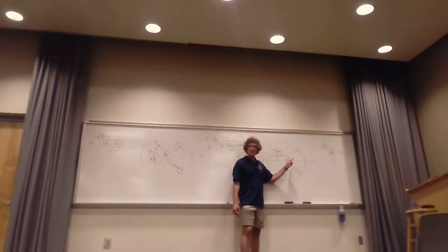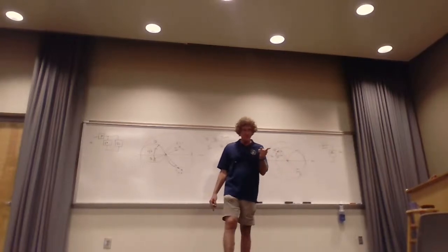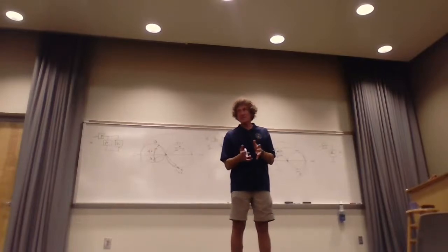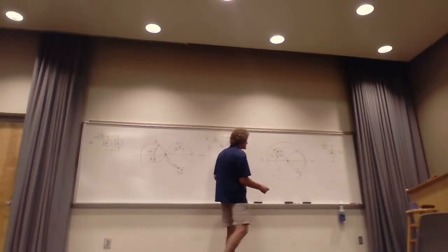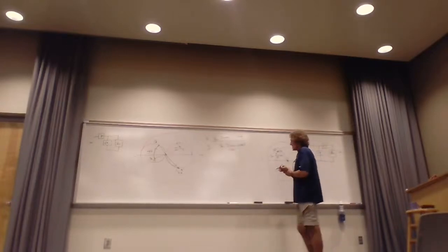Y'all follow me on that, class? Does anybody not follow me? Okay, remember that. Admittance, right? The inductance, if you add it, would be a minus j. The capacitance would be a plus j, because admittance is 1 over impedance. And then you would add a plus j value until you got right here. So here, you're going to have some plus j, and I'll just call it B. And then it's matched, at that one frequency.